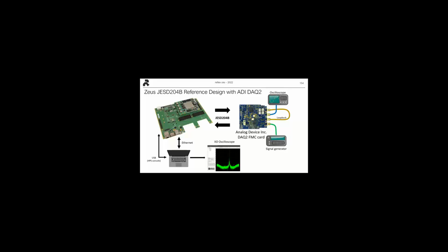And the good thing is, if, for example, that proof of concept board is working, maybe you need to change a little bit the form factor, the size, the features on it, and you want to directly go to a chip-on-board approach. You can just remove the FMC here and put the analog converter.